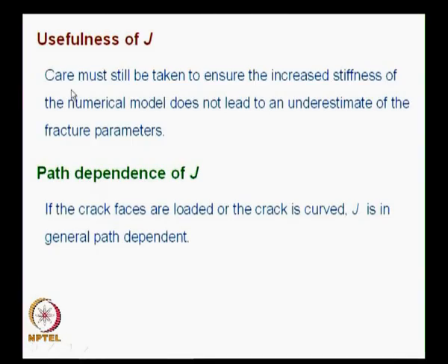See, in the case of finite element computation, you take a convenient path and then evaluate the value of J. You will have to keep in mind, care must still be taken to ensure the increased stiffness of the numerical model does not lead to an underestimate of the fracture parameters. So, people will do reduced integration technique, a combination of that they will do, they will go through the Gauss points away from the crack tip. So, there are some recommendations that you have to follow from finite element solution developers, and based on that you will have to evaluate J.